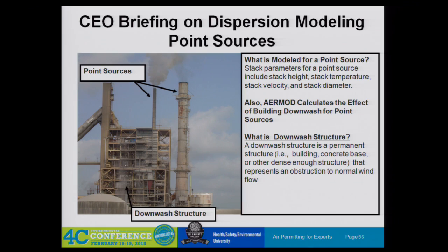All right. So these point sources, I'm going to kind of blow through some of this stuff. The model's fairly sophisticated. It takes into effect downwash influences, and that's just kind of the cavity turbulence zone where the wind's blowing through a building. There are some downwash effects or cavity effects. So you put in your building dimensions to account for that, and there are numerous algorithms that calculate it. At times that actually helps your dispersion. It distributes over the length of the building. At times it hurts it. It brings the plume down to ground level faster than it would normally be